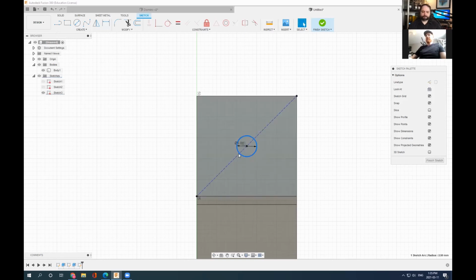But what I would like to do first is bisect this circle because we're going to use that to make our revolve cut, and we'll get into that later. So you're going to go back and select the line tool. You're going to want that one to be a solid line, so you're going to go over here and not do like I did and not convert it. And you're going to find where the intersection of your construction line and your circle are on the circumference. And you're just going to drag again and pull across and click again. Now you'll see, hopefully you all have it, you have a circle with a bisecting line, and you should be able to then click on just one half of the circle. That's quite important at this moment. So make sure you're along there with us.